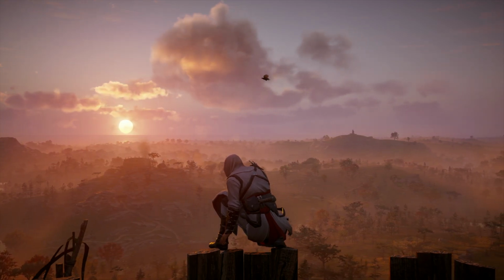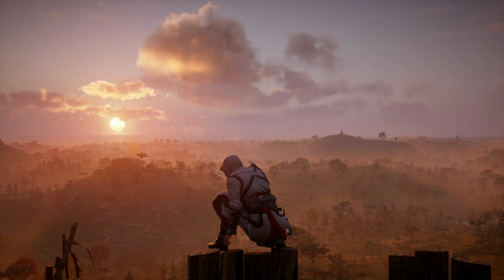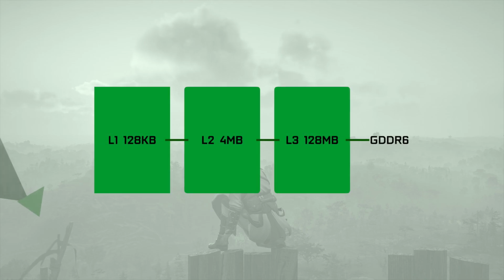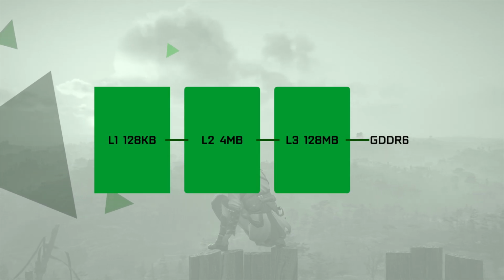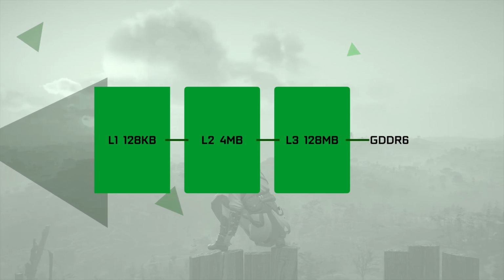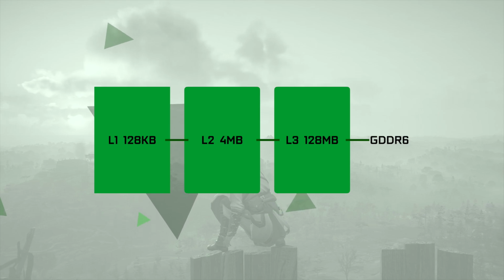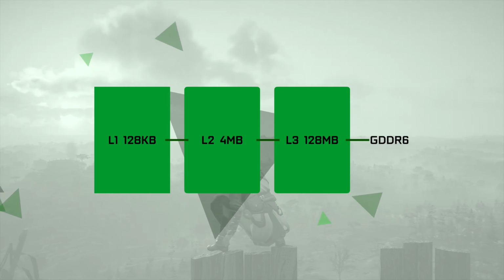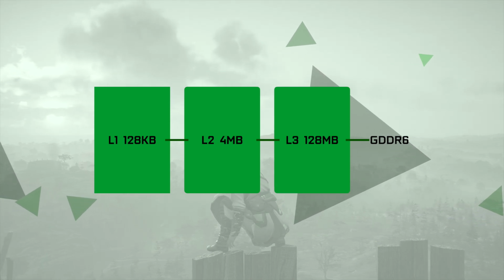One of the most ambitious innovations of the RDNA 2 architecture is a new cache hierarchy. Multiple low-level cache structures are connected to a few separate buffers of L1 cache, which are 128 KB per shader engine. Then there is a 4 MB buffer of L2 across the GPU and a new L3 cache structure called Infinity Cache that reaches up to a 128 MB buffer size in top-tier cards.